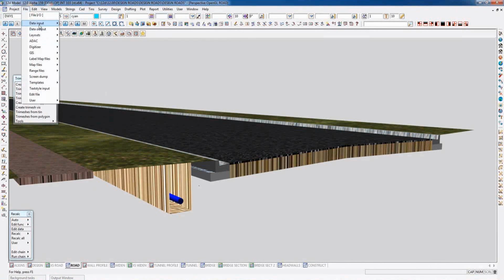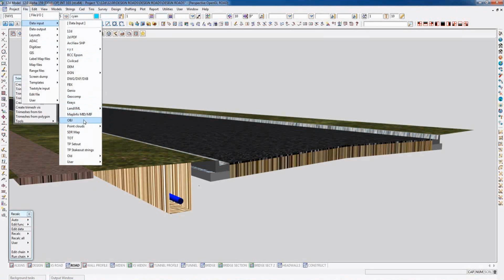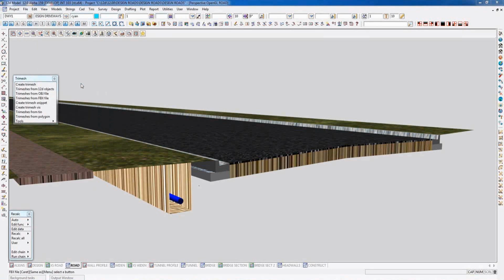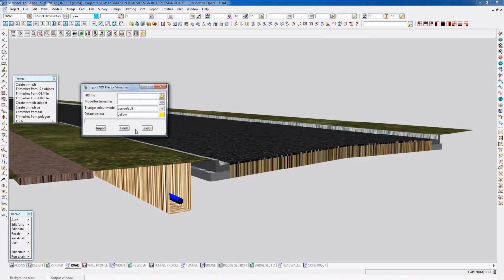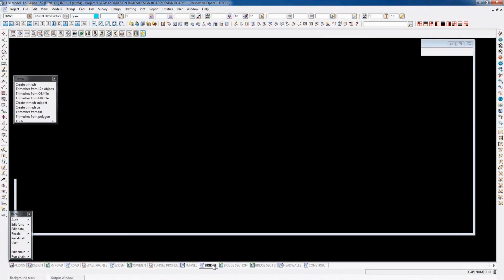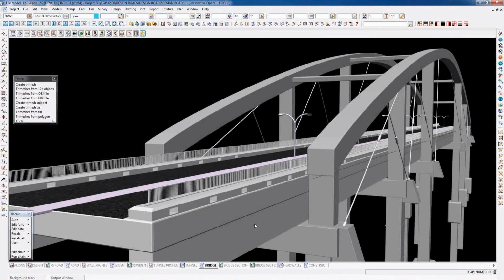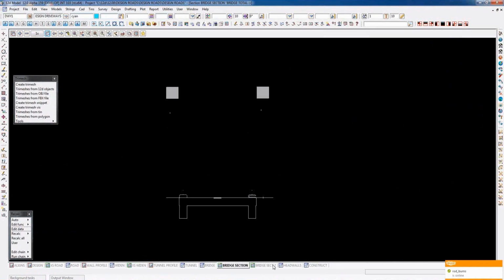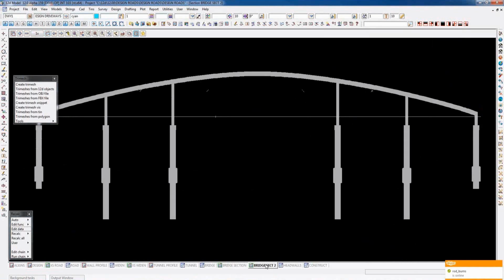The data input and the FBX automatically asks you for a model for Trimeshes, so then you can end up with options like this being read in, and again, with being a Trimesh now, you can then section through the Trimesh and get a good idea of the shape, and also if you're after clearances. So we'll go back to our